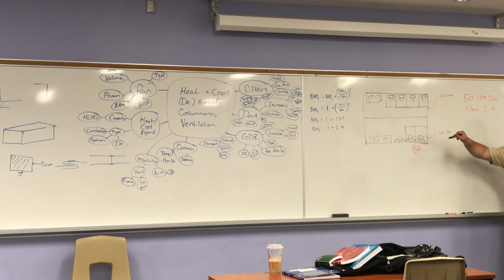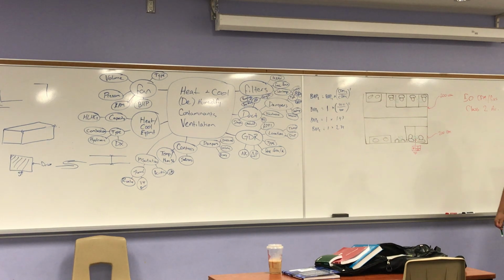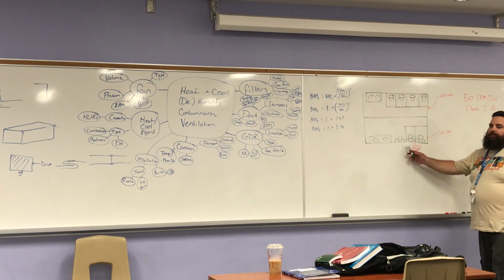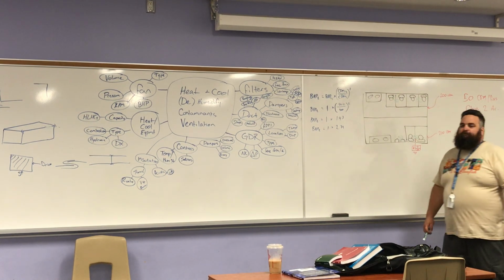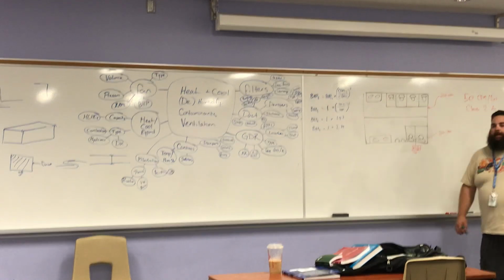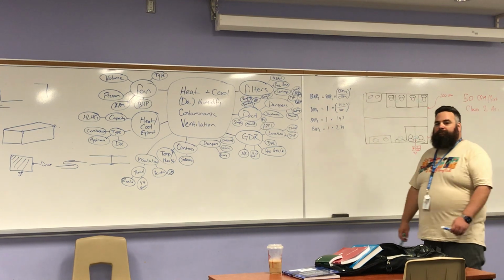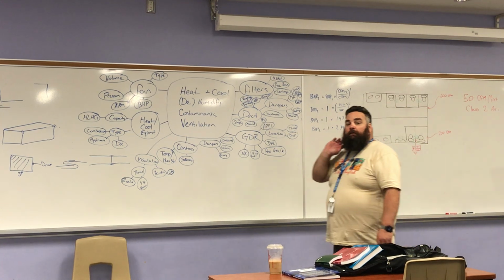So, I've got my inlets. Where's that air gonna go? Well, can class 2 be recirculated? Class 2 cannot be filtered and recirculated. Okay, so it would be exhausted. Be exhausted to the outside. Okay? Where do we want to exhaust to the outside? Probably far from an intake. Sorry? Pretty far from an intake.